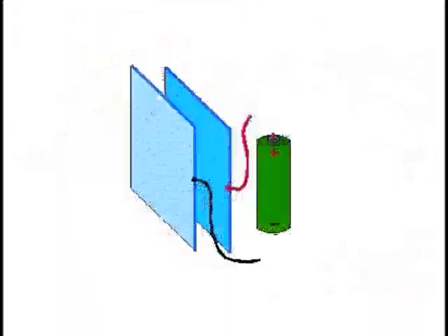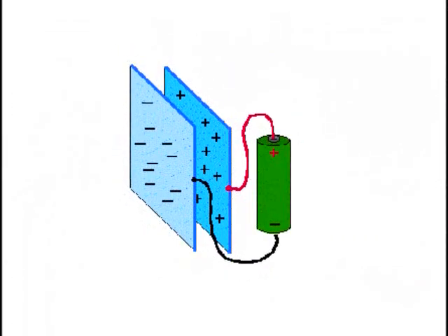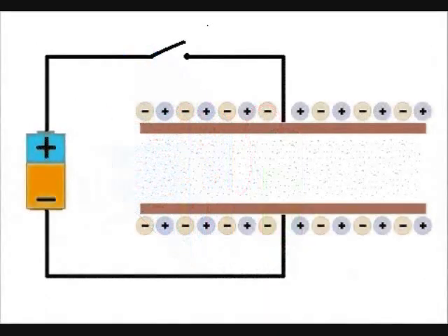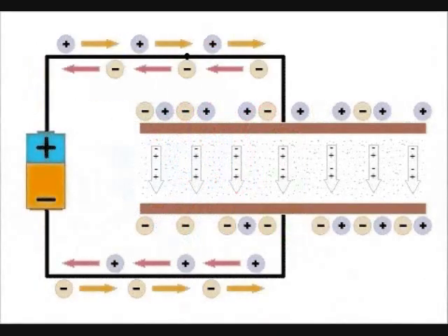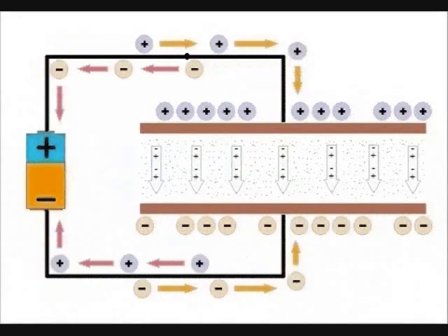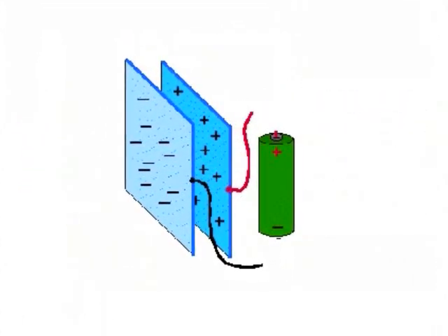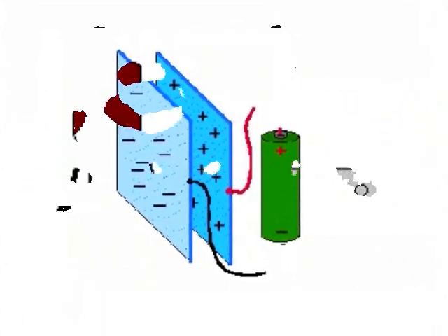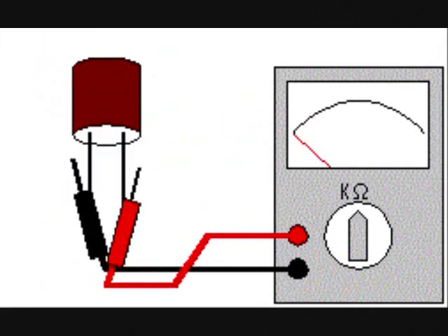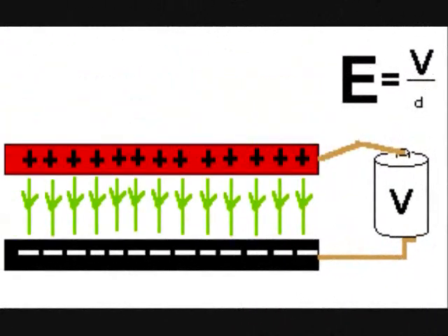When a capacitor is in electrical equilibrium, none of its plates have an electrical charge. When we charge it, the electric charge Q moves between the plates. This displacement causes one plate to be charged with +Q and the other with -Q. Considering that we are dealing with two charged plates, a potential difference can be defined for it. Note that in the following we will denote this potential difference by delta V. It is also clear that the net charge on the capacitor is always zero, and it is only the charge distribution that leads to the potential difference.